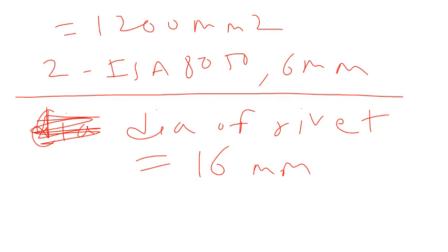So gross diameter will be equal to 17.5 mm. This is done to maintain the proper distance between the rivets and to maintain the proper edge distances. Here number of rivets will be little bit more. So next job is to find out the A net.